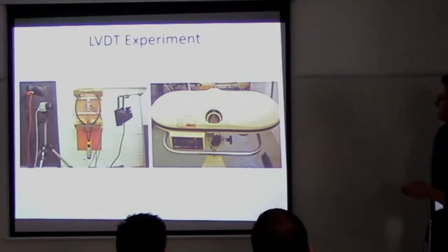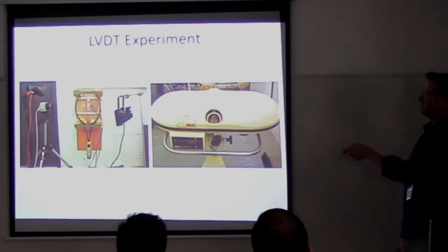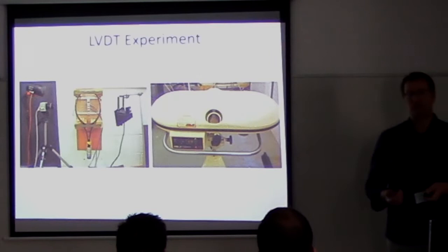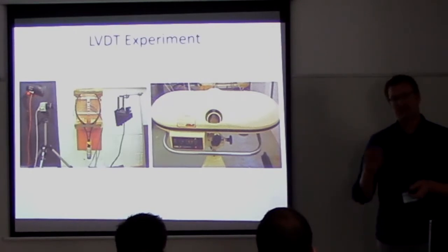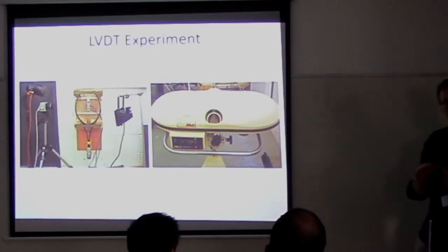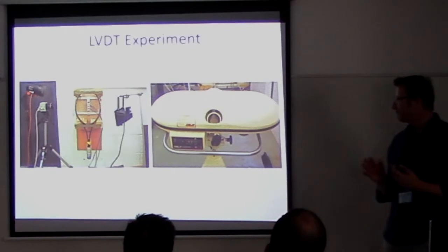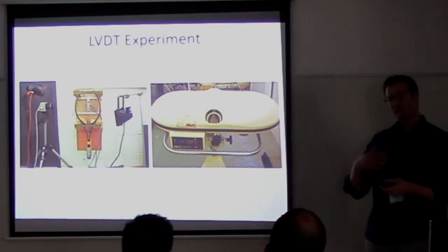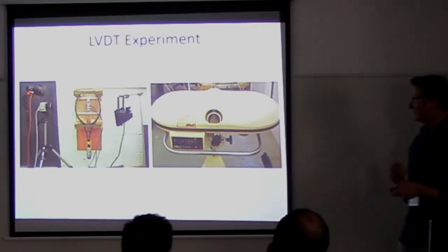The LVDTs would be attached behind the racket. You have here a high-speed camera, because one of the issues with the LVDT is that you have to have a carrier frequency, and the carrier frequency against the mechanical measurement is only given as a rough approximation of 10-to-1 accuracy. So we weren't sure whether this would respond quickly enough to the vibrations